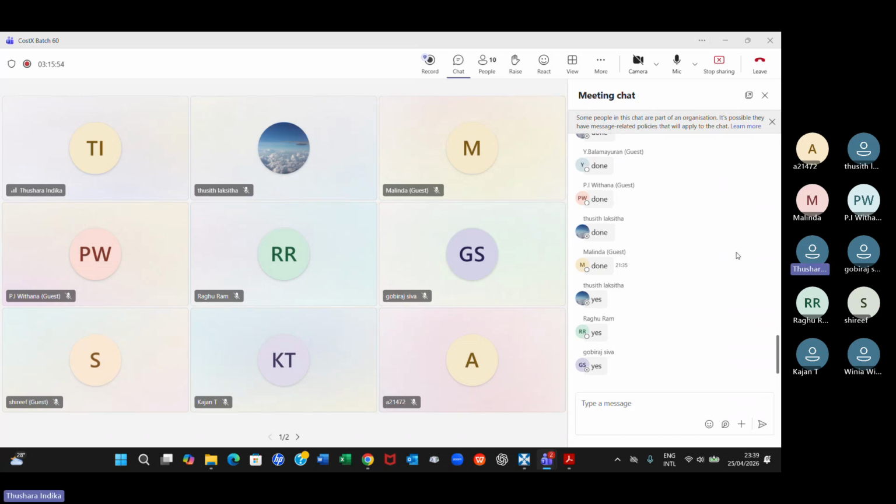All okay. We basically looked at how to price a BOQ, right, using rate library. And what we have learned is you can't import details from Excel directly into CostX. So what you need to do is convert Excel files into CSV files before that. Then once you convert it, you can import into CostX.